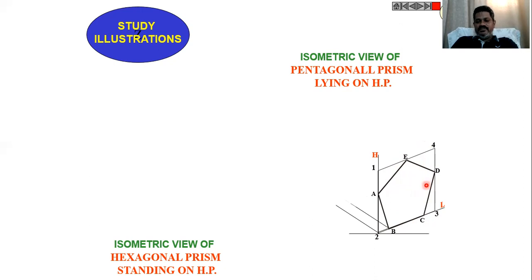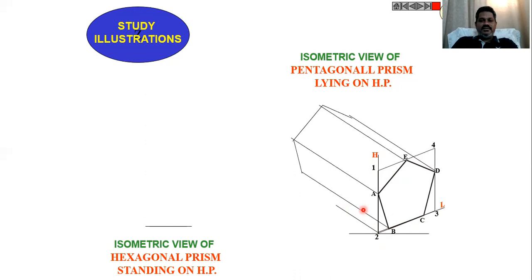Now construct the pentagon. Then in the problem, definitely the height of the prism will be given. So with that height, from points A, B, C, D, E, draw the lines which are parallel to this line, to the depth. This will become length and this will become depth. So with that depth, draw the lines and connect all those end points, which gives us the isometric view of the pentagonal prism, one of the faces lying on HP.